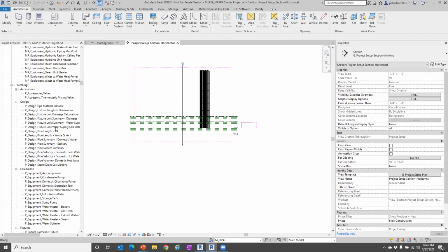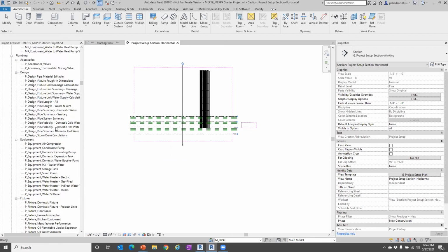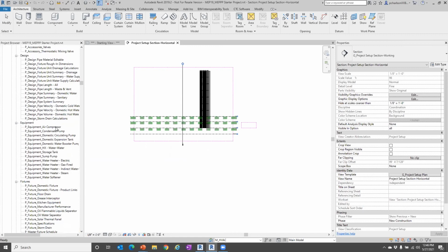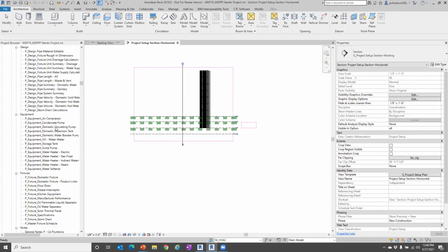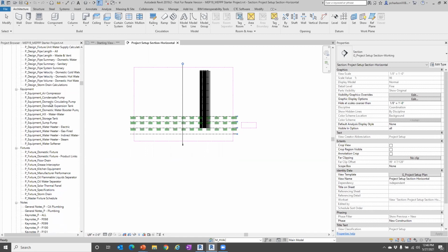You can obviously show things a little bit differently within a working type view over a construction document type view. What I determine a construction document type view to be is, again, the view that gets placed on a sheet, and it is also set to the way that your company has their standards, how you want to look at items within there.